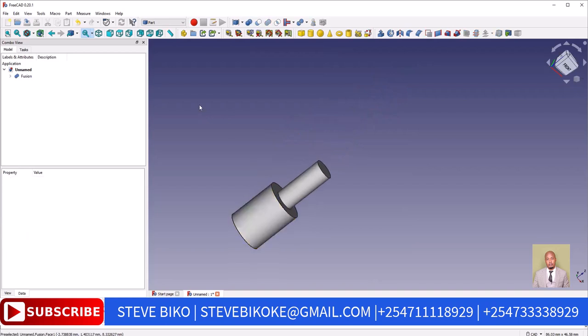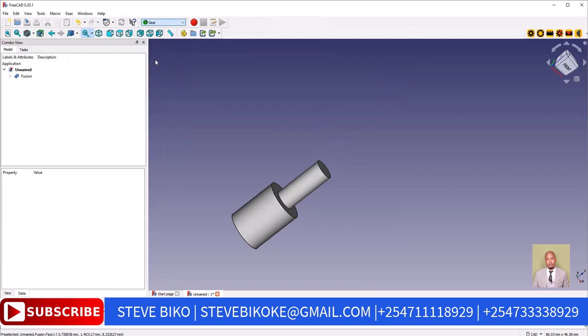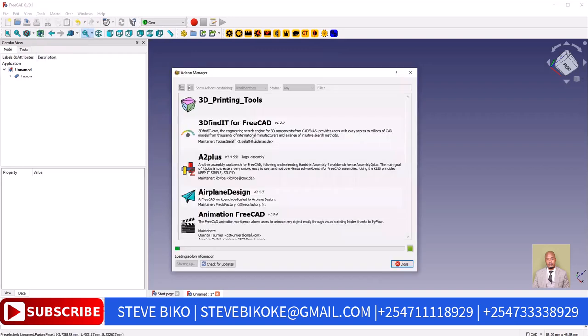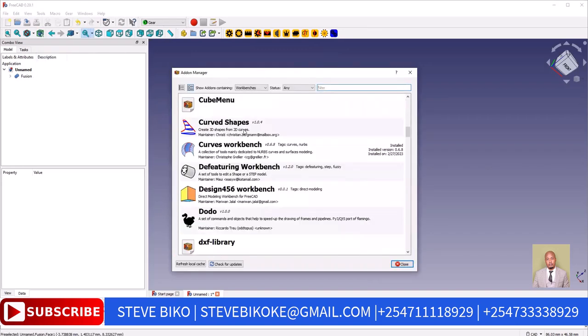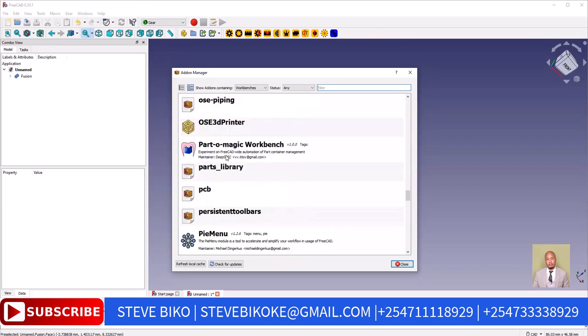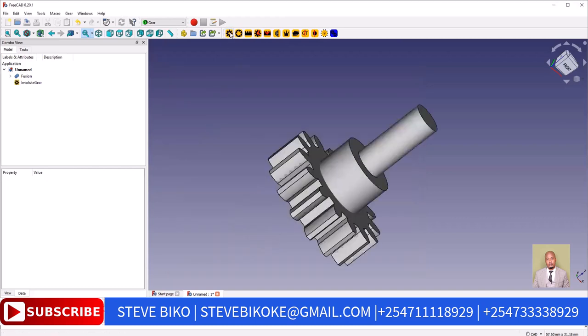Then from there, we will go to the gears command, which is here. But if you still don't have it in your software, you can go to Tools, then you click on Add-ons, and you can always look for it here. It is called FreeCAD gears, somewhere. Then if you've not installed it yet, you can just click on it, then you install. Good, let's proceed. So we'll select the gear.